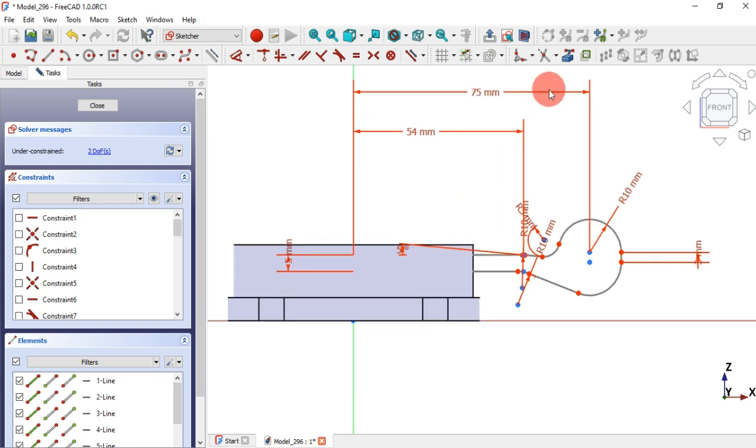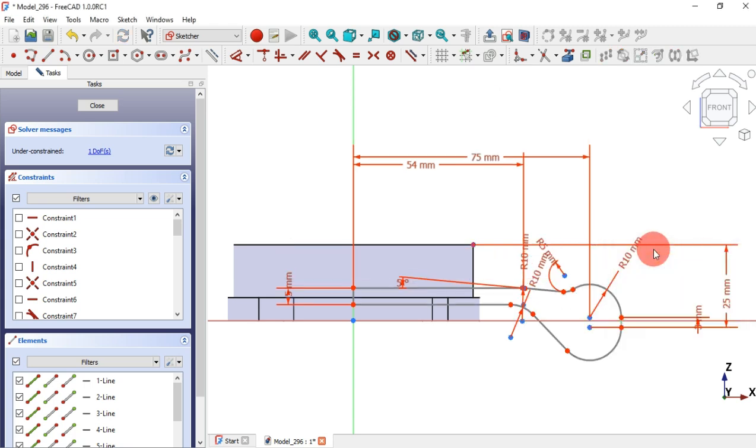So next, select external jump tool and extract this edge here, and now we have this endpoint here. Switch to the session view and then select this tool again, and now just click in this point here and in this endpoint, and let's create a vertical dimension. Just click here in this point and set 25 millimeters, and as you can see, we have this.